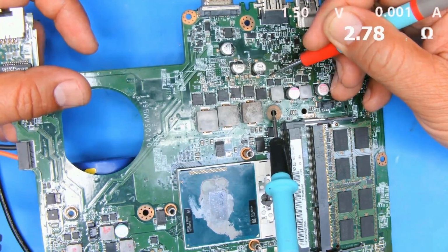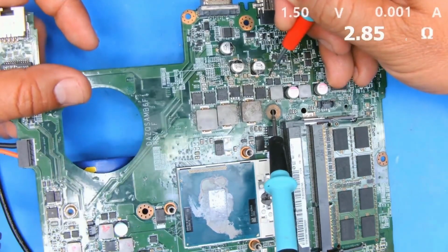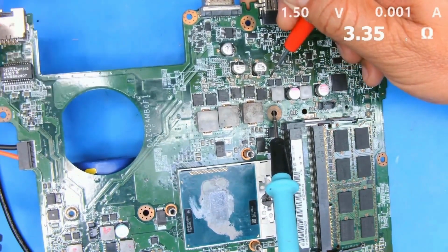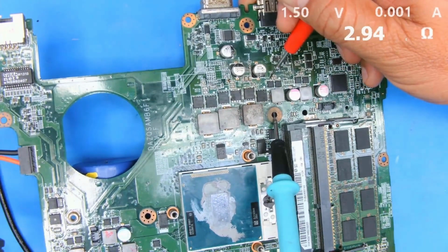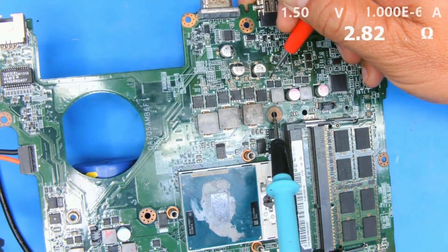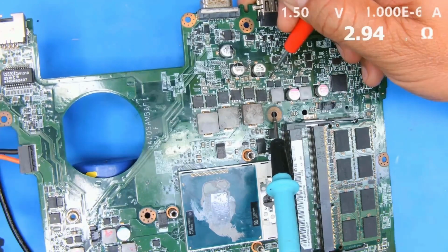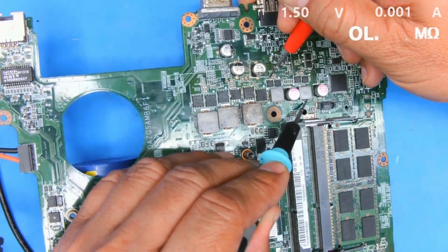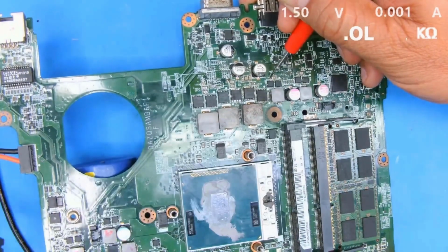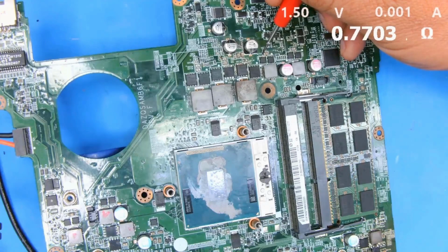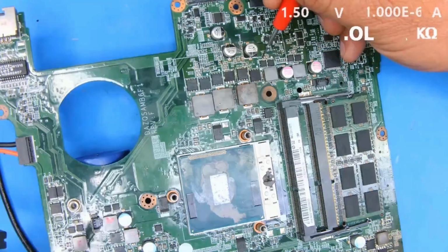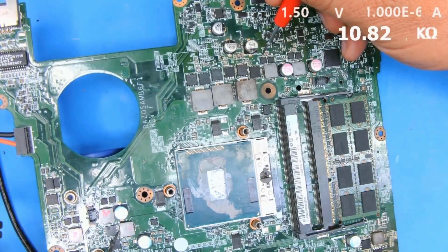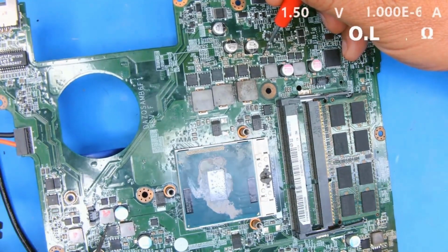For the repair inspection method, you can measure in ohms. I recommend measuring in ohms, or you can measure in diode mode. In cases where it reads exactly 0.0000 volts, I suggest measuring in ohms as it's easier. After touching the probes, move the probe to another point and see if here, it's absolutely 0 in front, precisely 0 ohms in front. The actual ohm value here is approximately 0.4 kilo ohms, which specifically refers to this particular point. Other points are definitely not 0 ohms. They're about 10 ohms, something like that.